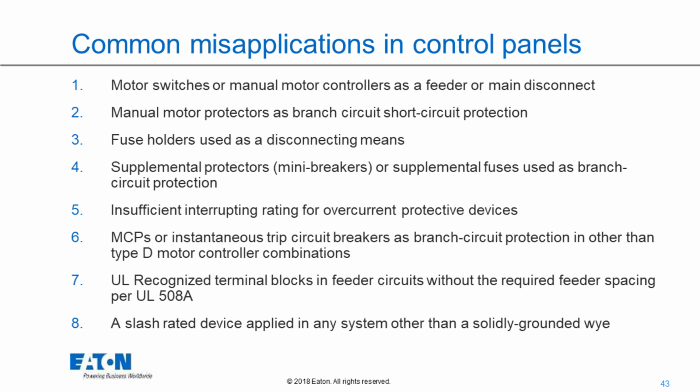UL recognized terminal blocks in feeder circuits without the required feeder spacing per UL 508A. Slash rated devices applied in any system other than solidly grounded Y systems. Like we went over, the ungrounded delta, corner grounded delta, and high resistance grounded systems can't use slash rated devices.